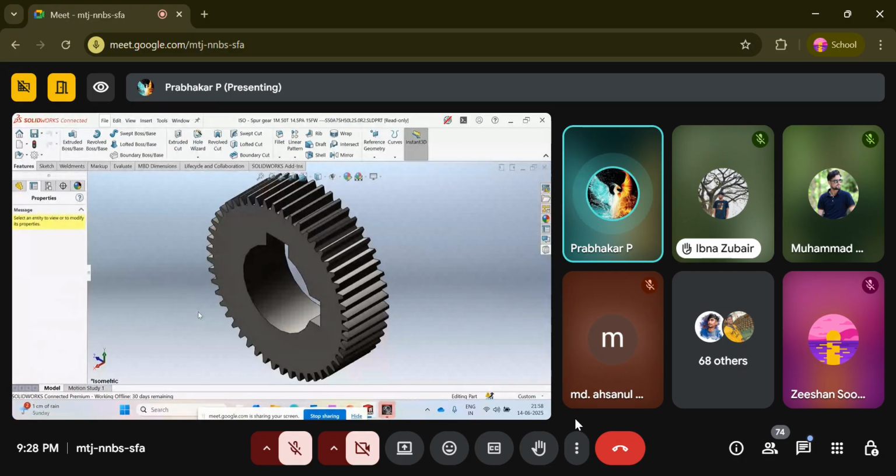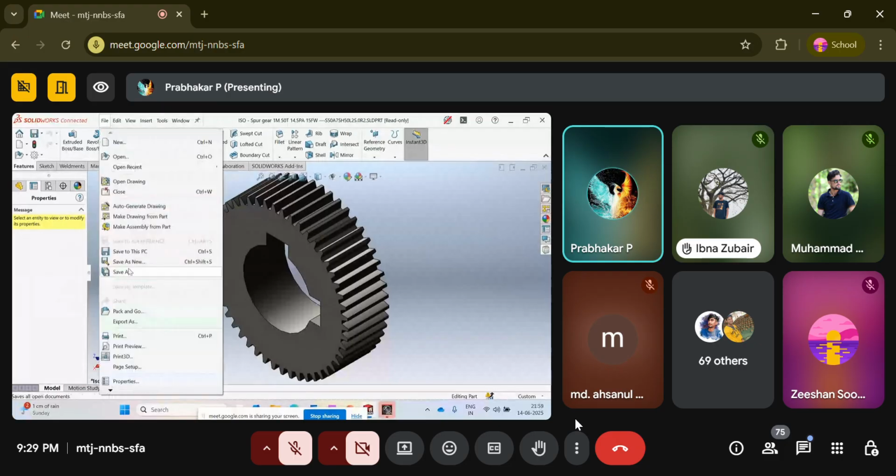These two gearboxes give a very high gear ratio, because you can see here the PCD is 50 mm. The other gear, if I draw with 300 mm, the PCD will be 300. The center to center distance will be 150 plus 25, which is half of this. 175 will be the center to center distance between these. Okay, so now I will go with the spur gear only, and I will just create it and show you now. Save as new.